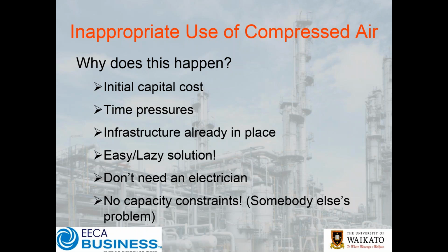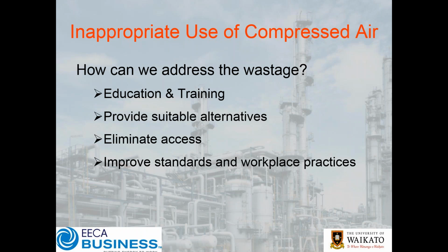The great thing with compressed air is you don't need an electrician. You don't need another connection at the MCC to hook up another piece of kit. And the other thing, of course, is generally speaking, everyone ignores the fact that there is still a capacity constraint. So we have this perceived no problems, plenty of air, no capacity constraint. When in reality, what we're doing is we're making it somebody else's problem, because at some point you will run out of compressed air.